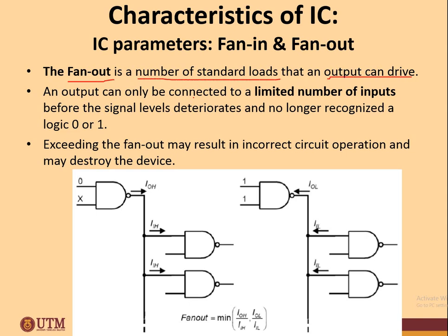An output can only be connected to a limited number of inputs. This is very understandable. If you have one chip, you cannot connect it to an infinite number of chips, not 10 chips or even 8 chips. You need to consider the fan out. Maybe the gate can only support up to 5 gates at its output.